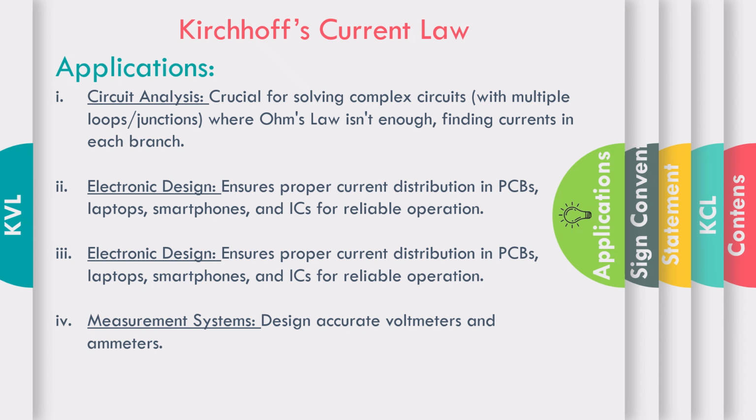If your circuit is only one loop, Ohm's law is applicable. But if your circuit is a complex network with two or more loops, in that case we find the current through each branch, and we can use Kirchhoff's current law at a particular junction point.